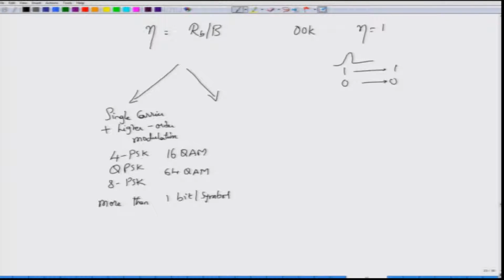With 4 PSK, which we have described in one of the earlier modules, you have options of 4 states. 4 phase values, this is the I and the Q axis of the system that we have looked at. These points are called the constellation points, and the entire thing is called the constellation. We have looked at all this in one of the earlier modules. With these 4 phase states for the 4 PSK, it is possible to associate 2 bits per symbol. If you prefer a gray coded version in which the 2 symbols differ only by 1 bit, this is the so called gray coding approach.